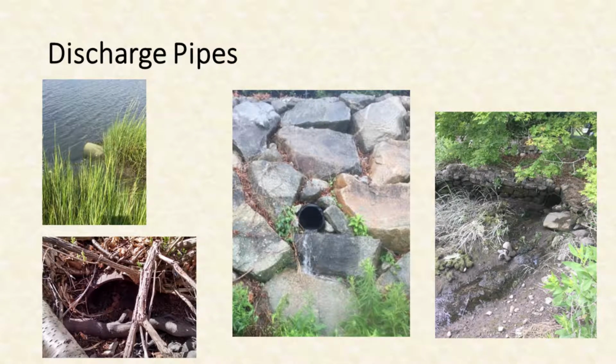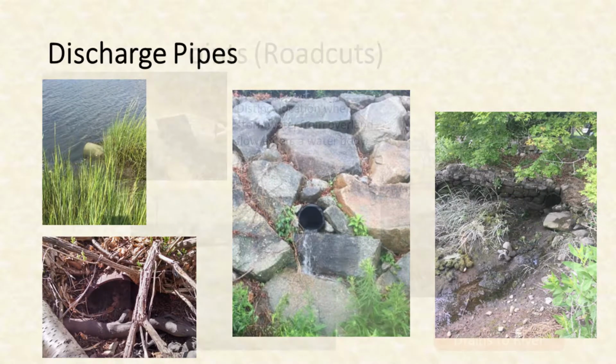Storm drain networks typically discharge to uplands, stormwater management structures, surface waters, wetlands, streams, or coastal waters. Discharge pipes vary in design and size and can be difficult to locate in the field. Some are obscured by thick vegetation or buried by debris or soil. In coastal areas, discharges are often impacted by tidal changes. Many cannot be found even during low tide.